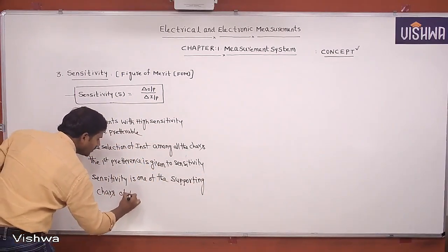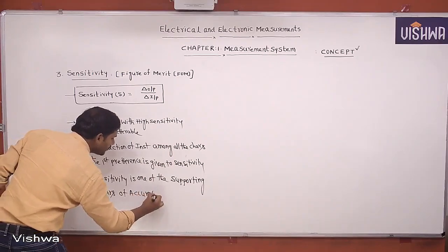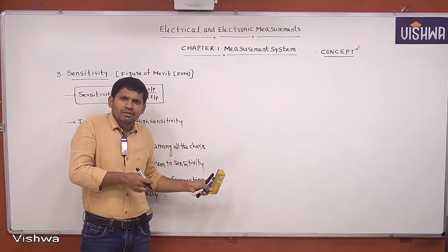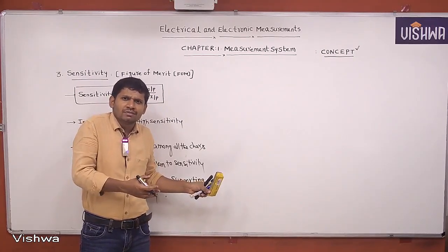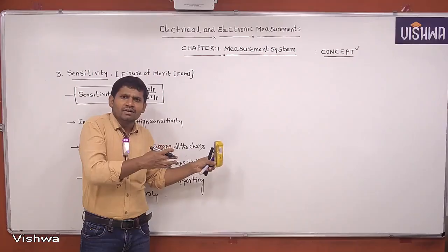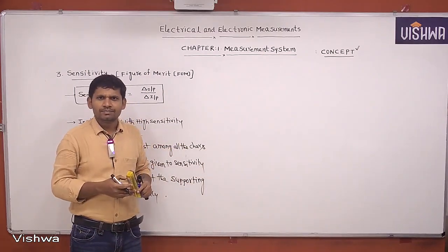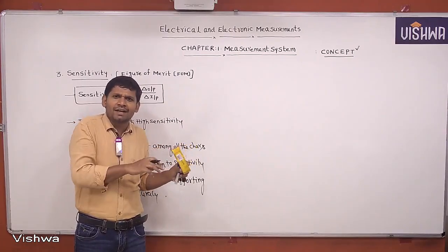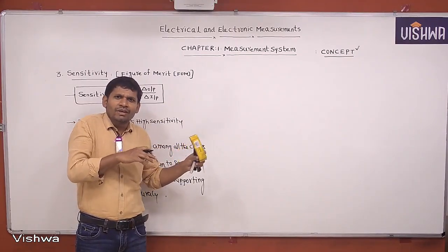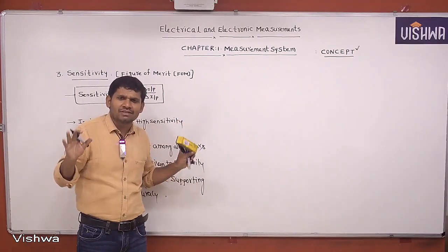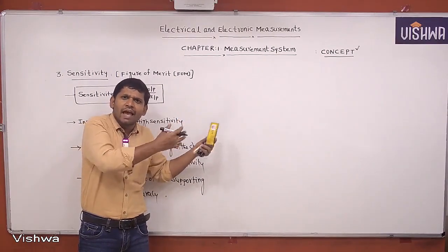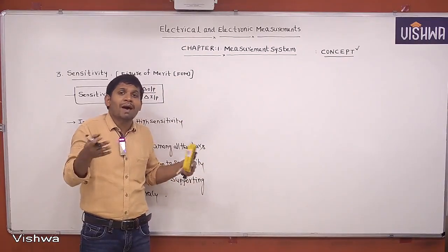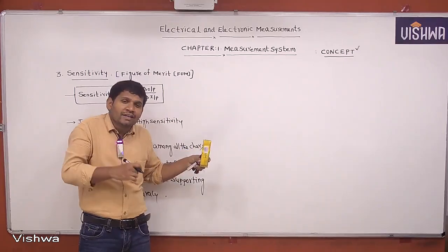One simple example using the bridge itself. For a small change in resistance, the bridge is unbalanced. If it is detected, then we can measure the exact value. If for a small change in resistance the galvanometer does not detect it, then we can think the bridge is balanced even though there is a change in resistance.